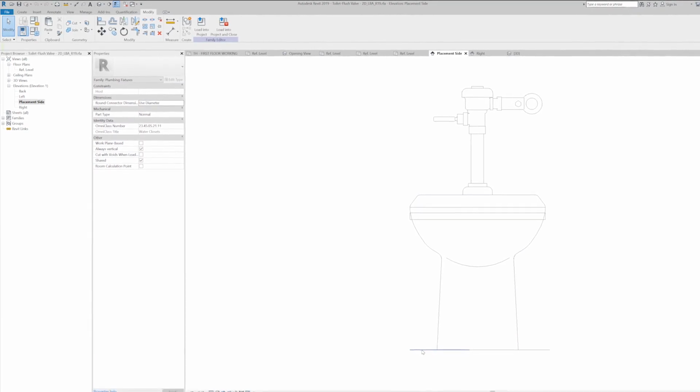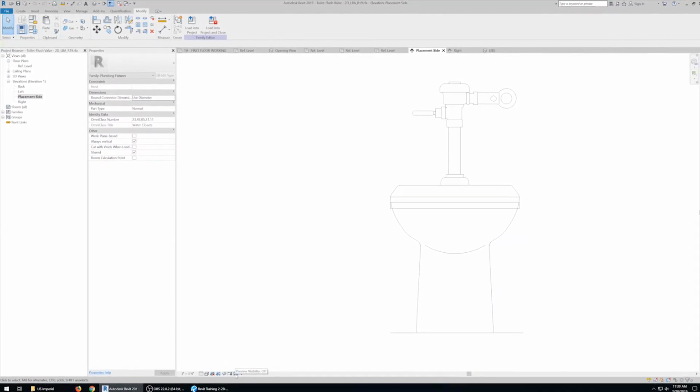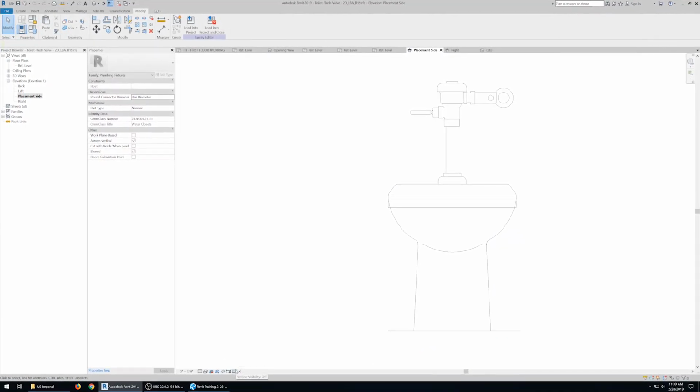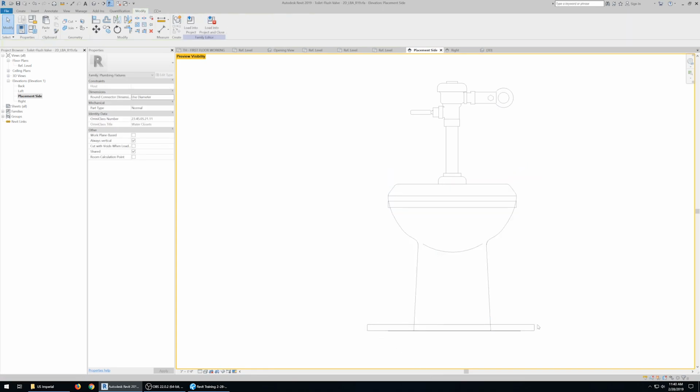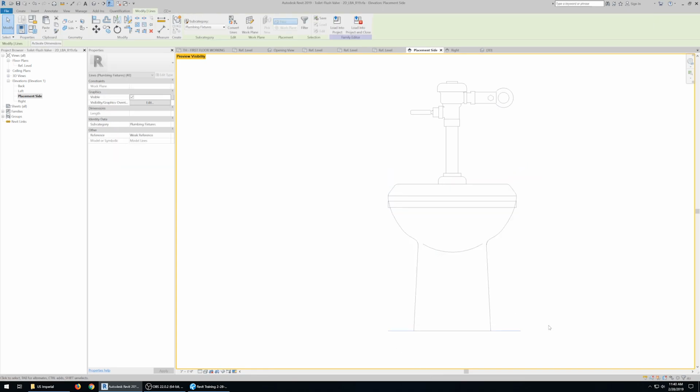Well, you're not going to see it because it'll be on the floor, but there is a tool inside, and this is relatively new. I want to say in the last two versions, but there's a preview visibility function at the bottom in the family editor that allows you to turn it on. And when you turn it on, it's supposed to turn off, and it did, with the exception of these guys, which are symbolic lines anyways. That's probably why, but they still shouldn't be showing in elevation.